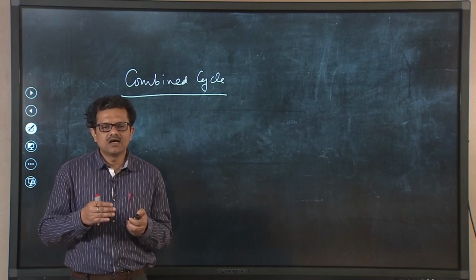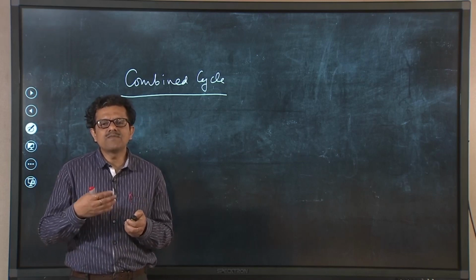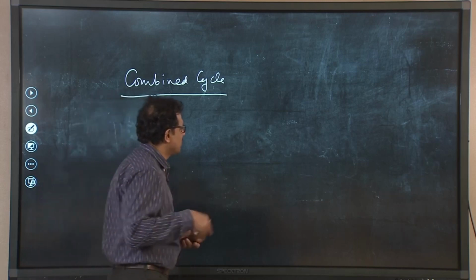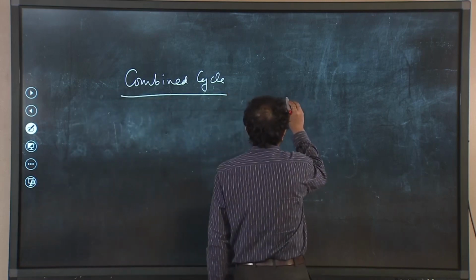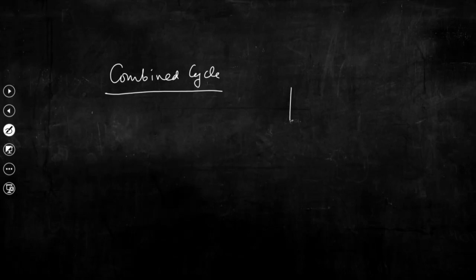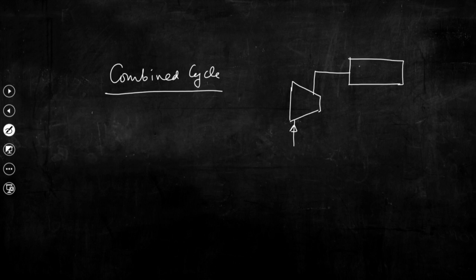So, now question is, despite having a few disadvantageous features, still there are some advantages, and accounting for this advantageous feature comes a new concept, that is the use of combined cycle. What is done here? We had seen that if we consider this is the compressor, then we are having combustion chamber, we are supplying certain amount of Q in, as if we are supplying fuel, and we are supplying certain amount of heat.